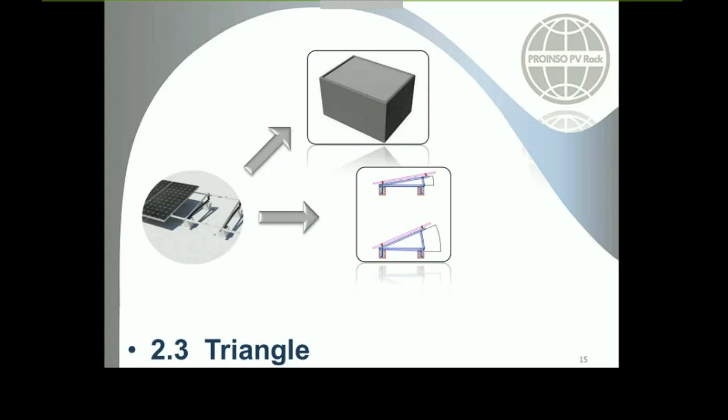You have to take into account the tilt of the structure and the height of the building, and this way we calculate the loads transferred to the bottom of our structure. When you have these reactions at the bottom side, you calculate the weight to avoid the structure going up. Do you know what I mean?